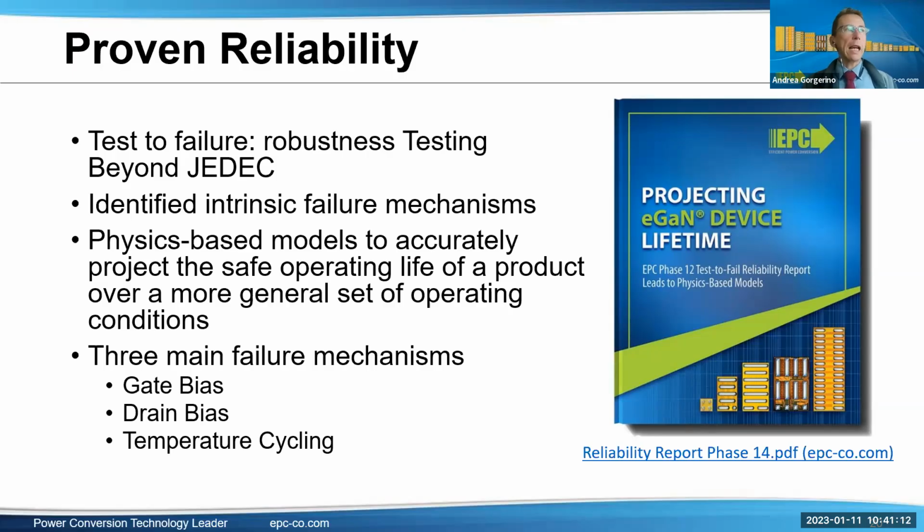So we have found that with proper design techniques, which means proper layout techniques mainly, we can have extremely clean waveforms. This is one of the advantages of GaN FETs. They're very linear. They have extremely low parasitics, especially, all of our packages have very, very low common source inductance, which really allows us to have very clean waveforms during switching events, which reduces the ringing.